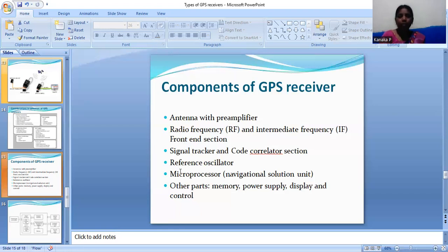Next: angular measurements, distance measurements, and slope distance. First one is angle measurements. All the components of an electronic theodolite are found in a total station. The axes of the configuration are identified in comparison with the vertical axis, pointing axis, and the line of sight. Other components include the tripod with leveling screws, keyboard with display, and the telescope, which is mounted on the standard and rotates around the tilting axis.